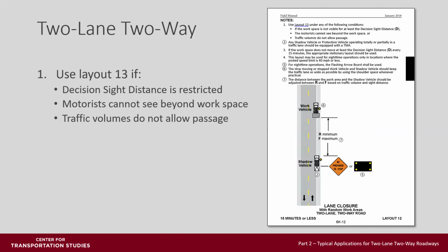Layout 12 is for a lane closure for 15 minutes or less, a mobile operation on a two-lane, two-way road. And if you don't have a good decision sight distance, use layout 13.